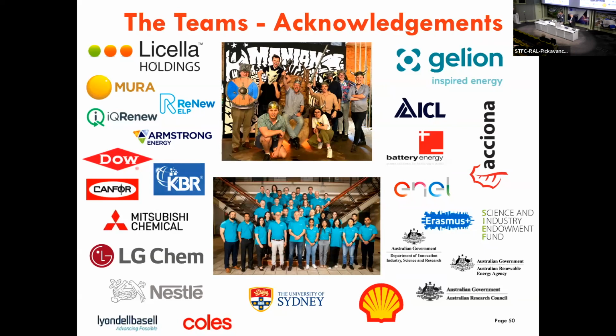So supercritical water, yes, in passing. It's about 450 degrees the way we use it, and 220 bars, and the water itself becomes really aggressive. But it also is able to donate its hydrogen. And that's a good research question actually, to really see proton radicals under those conditions, to prove what must happen retrospectively, because you take plastic mixtures and go through normal pyrolysis, and what you get out is horrible. What we get out is a bit like baby oil, slightly colored, depending what we do. And that can only work if you stabilize the radicals that you're forming. The way that is most likely happening is from protons from the water. But really, really reactive water.